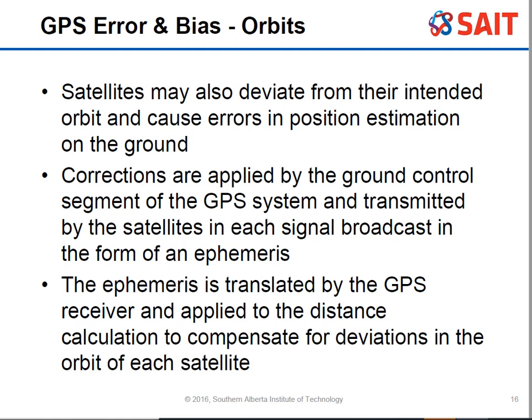And so there is a possibility that, if it's really urgent and really bad, they will use the fuel that's on board and move it over. Otherwise, because there's only so much fuel, they'll just let it run. And they'll just send the ephemeris information and say, hey, this is the compensation for where you were located. It's not like it's going to move it over all the time, because you do run out of fuel. So the satellite just stays where it is, and the ground control says, hey, change your code and tell us where you actually are.